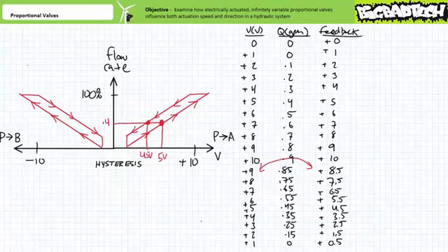On the way up, everything is copacetic and input directly corresponds to the desired output position. On the way down, however, there's a differential or error of 0.5 volts between applied voltage and the desired spool position. A sophisticated proportional valve can monitor this error and correct for hysteresis by causing more current to flow through the linear force motor and properly reposition the spool such that the error between applied voltage and spool position feedback is closer to 0 volts, regardless if voltage is ramping up or ramping down.